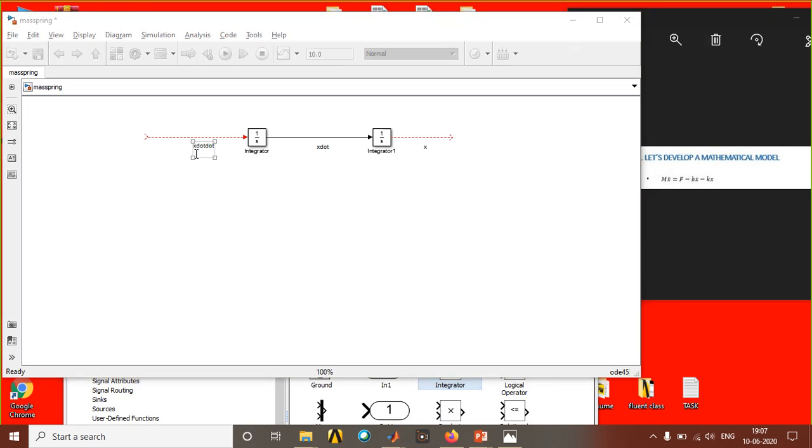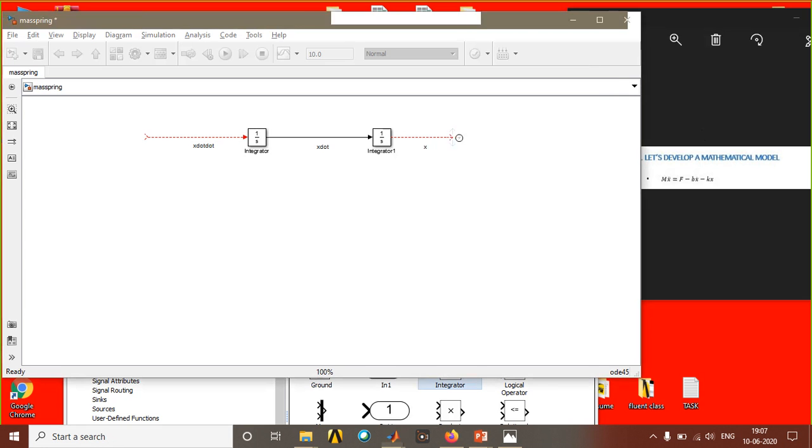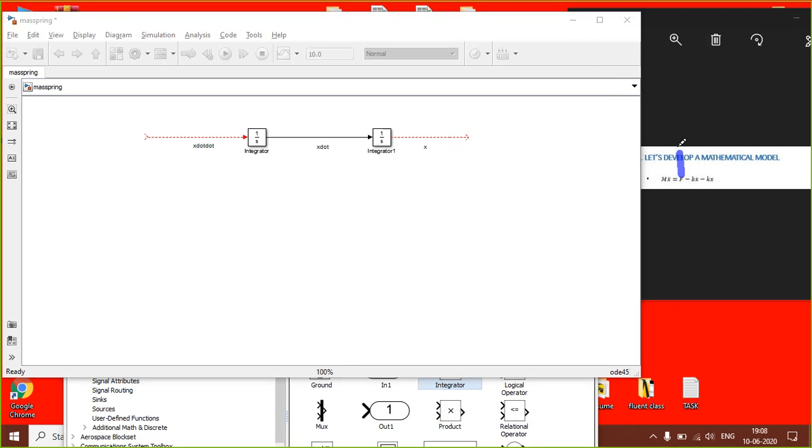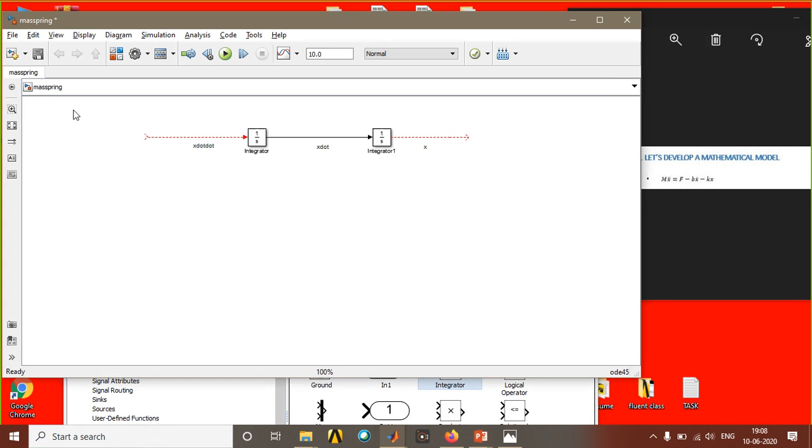What I am bringing as an input? I am bringing the output as an input. Okay, acceleration. Fine, good. This is what I need: x, the distance traveled by my spring. Next, what I am supposed to do? Go through this equation. We have three things. One, my F, force. Next, B, my damping coefficient, multiplied by my velocity. Next, my stiffness K multiplied by my x, distance. As you know, B is a damping coefficient constant, and K is a stiffness, which is a constant.